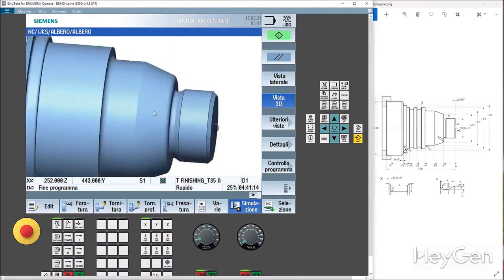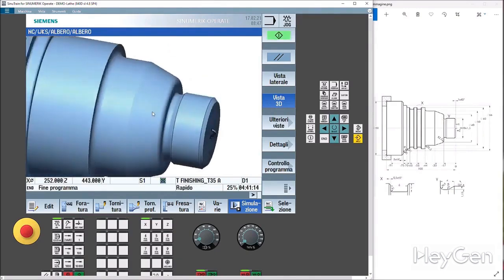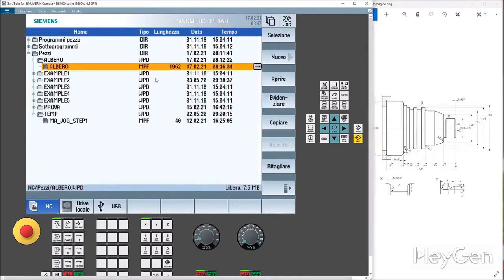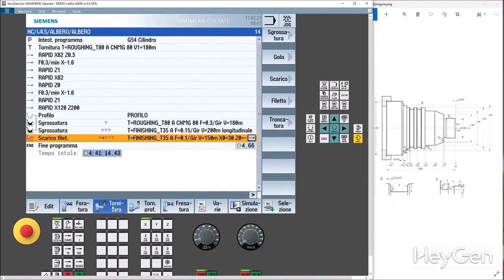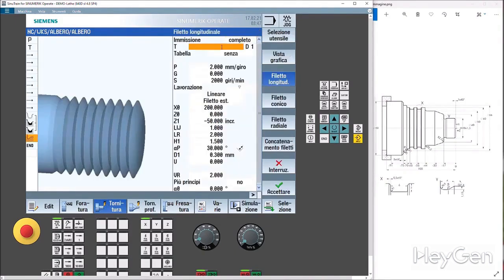All right. It's time to think about the thread. So let's select the turning thread soft key this time, which means the profile of the rest doesn't matter anymore, like it did for the unloading. I might not have mentioned it before, but we switched from turning for unloading because it's a standardized option.